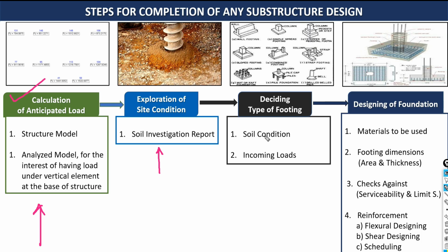What type of footing you have to consider for your project, for your structure, mainly depends on two basic things: soil condition and incoming load. In addition to this, economic consideration is also there. Economy is another most important consideration you need to take into account.